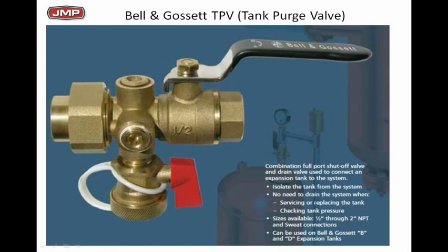So now we can also pre-charge the tank, and we can check the charge on the tank, even if the tank's still connected to the system. This should be standard on every detail out there. Every engineer in the world should put these things because it makes life easier. And if you get a problem with understanding what your pre-charge is, or you've got a bladder tank problem, this helps you with it tremendously. So it should be kind of mandatory every time you use a bladder tank.